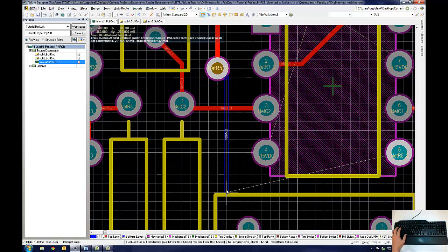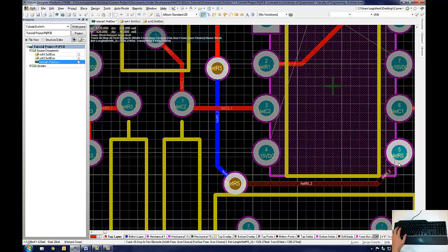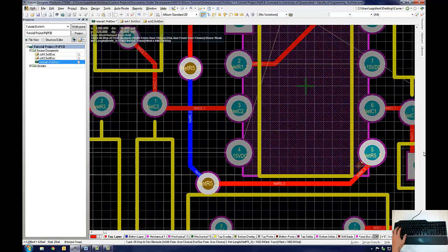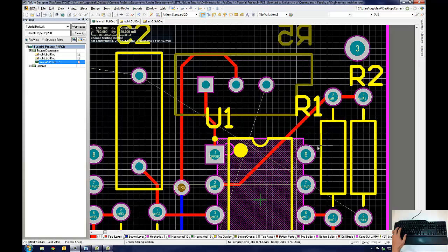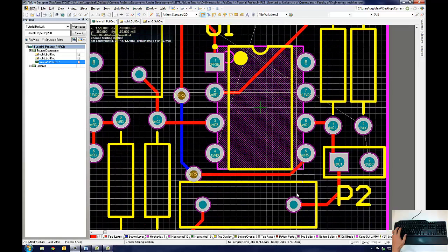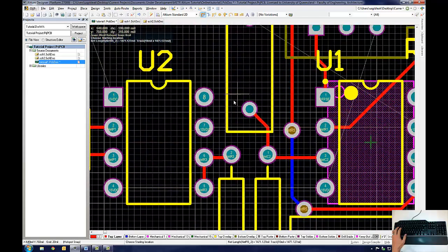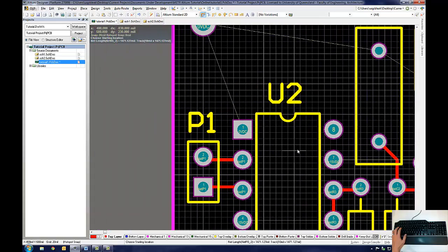It is common to use a via in the routing of long tracks across the board, as long tracks will encounter more obstacles. Once the user reaches the destination pad, they simply need to click the center of the pad to make the electrical connection. The track will continue to track until the user clicks the right mouse button once. The user can continue to route other tracks by clicking on a new pad and guiding the track as before.